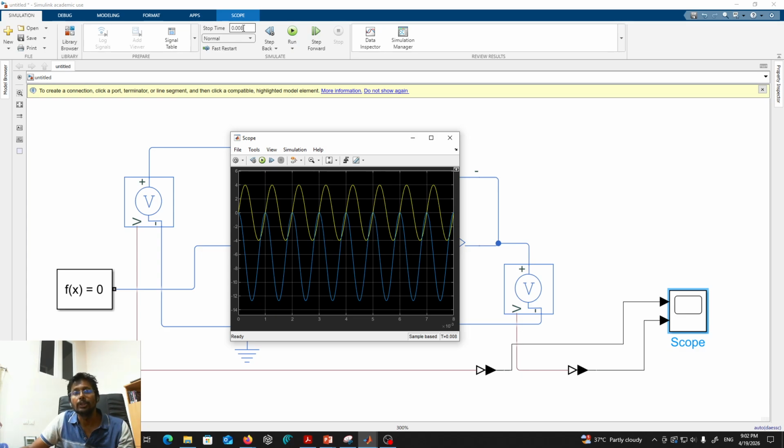The default value is 10, and we are giving the signal 1000 hertz, which means within 1 second you will see the 1000 peaks. So you cannot see this sinusoidal curve. You just see a band. So you need to choose the stop time according to your requirement.